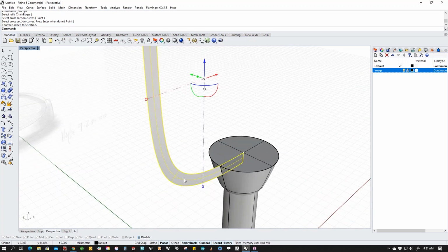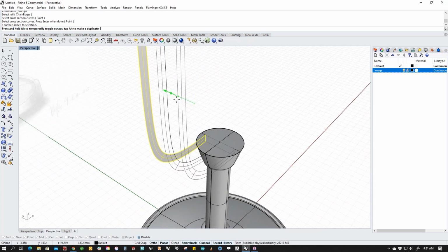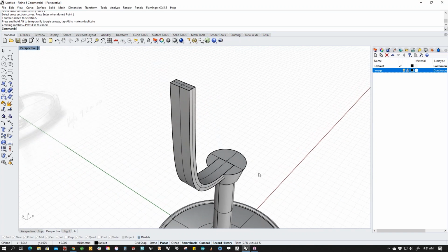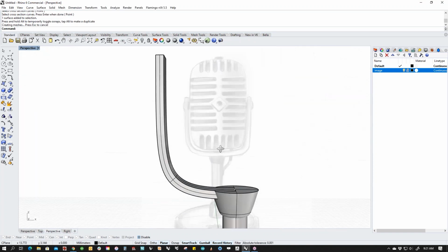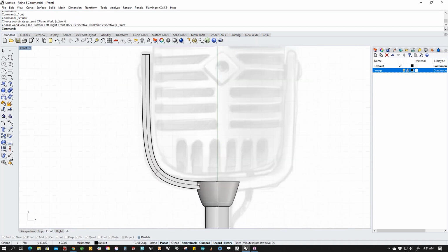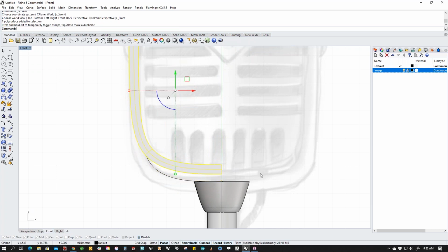Now we're going to do some gumball fun. I'm going to just start dragging from the dot, and I'm going to hold down Shift, and it's going to extrude in both directions. And then we've got a solid piece. Now, if I were looking at this, I would say that I probably need to take this and move it like that instead. And I'd like it to be precise.